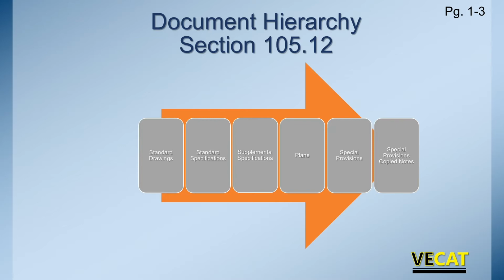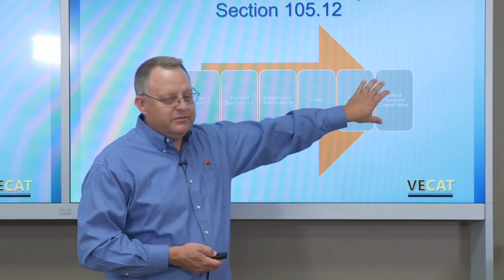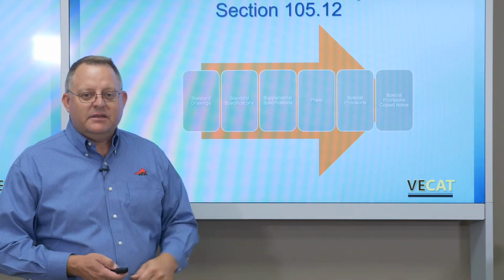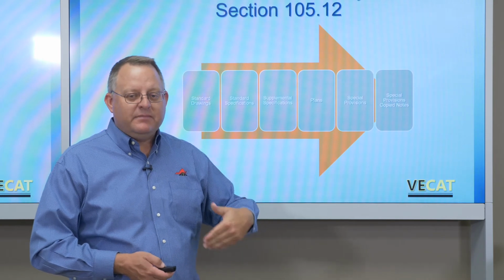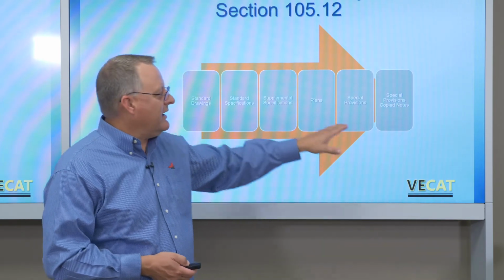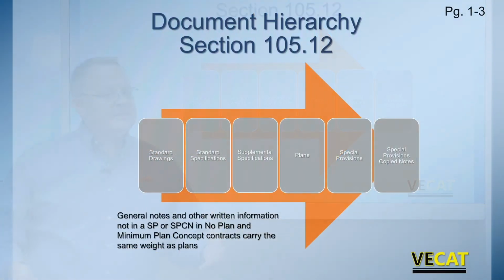And again, from the plant side, if there's something you need, maybe it has to do with the amount of limestone that can be used in a surface mix. Maybe there's a special project in Bristol where they're looking to use a different percentage. You need to be aware of that as you're doing your mix designs for the mix design technician, but you need to also be aware of that in case it impacts the testing that you're doing in level 2. Maybe it has different volumetric requirements.